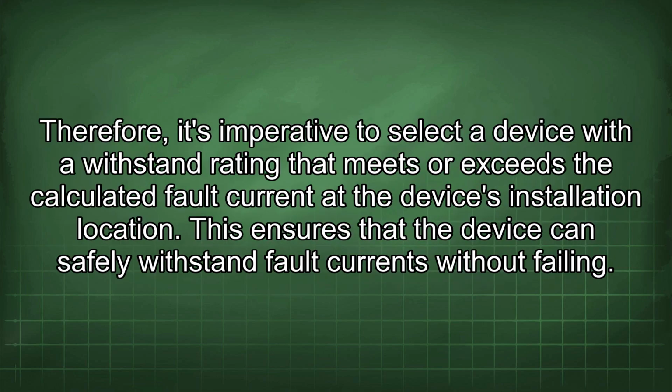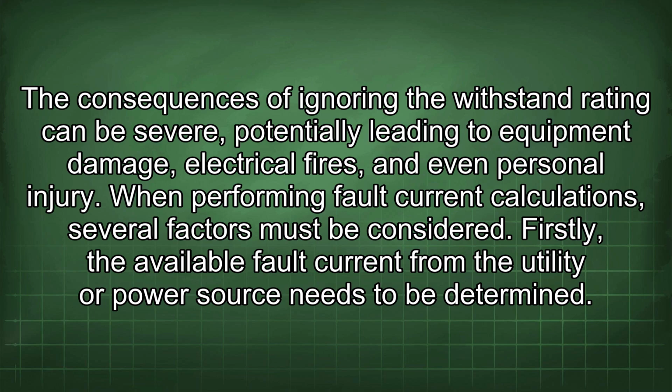Therefore, it's imperative to select a device with a withstand rating that meets or exceeds the calculated fault current at the device's installation location. This ensures that the device can safely withstand fault currents without failing. The consequences of ignoring the withstand rating can be severe, potentially leading to equipment damage, electrical fires, and even personal injury. When performing fault current calculations, several factors must be considered.